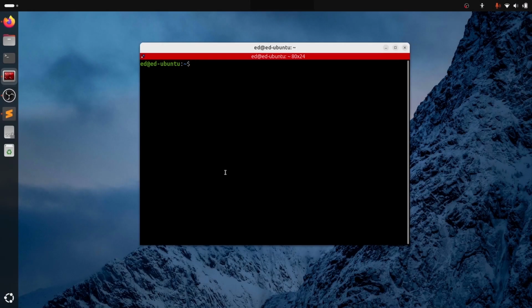To be able to configure the robot for MoveIt, we first need a URDF, which is what we already have, with the links and the joints. But in the links, we also need collision elements. For now, we only have visual elements. So here we are going to add the collision for each link.